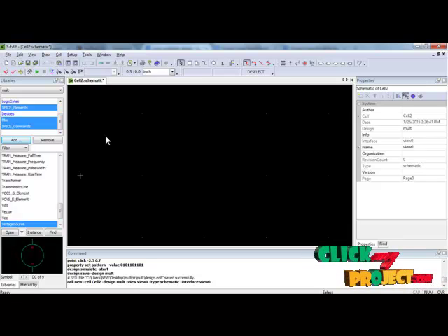After we design in SEdit, while simulating, the designed circuits will pass through the T-Spice, which we can understand through the netlist generated as SPICE code. Finally, while we are simulating, the timing diagrams will appear in WEdit. Hence, for our CMOS based designs, we will use mostly these: SEdit, LEdit, WEdit and T-Spice.